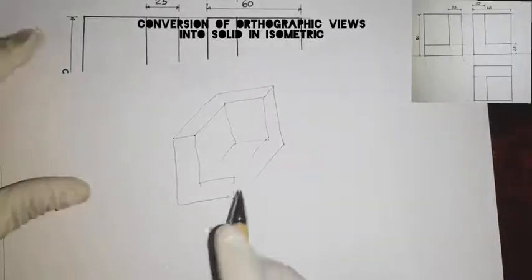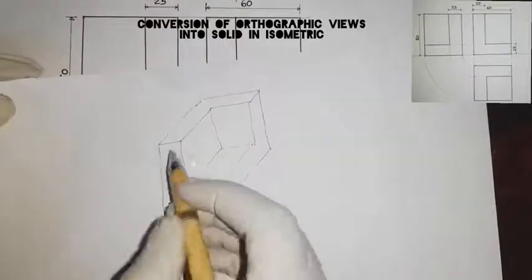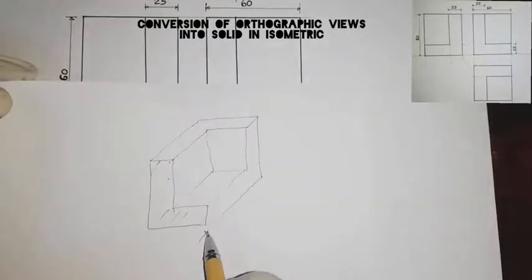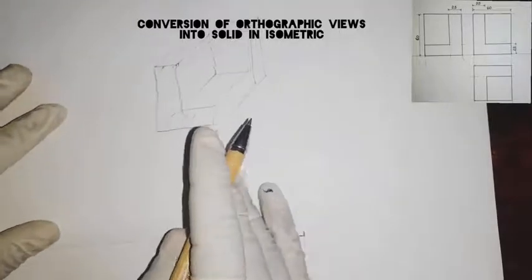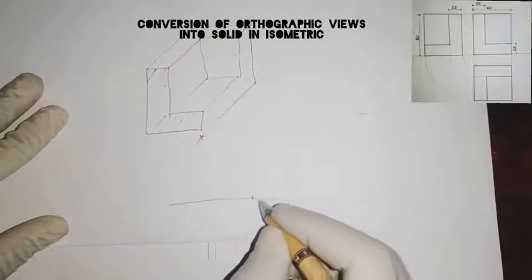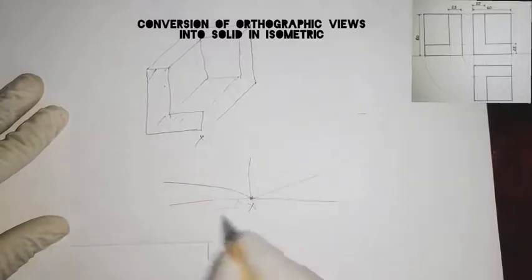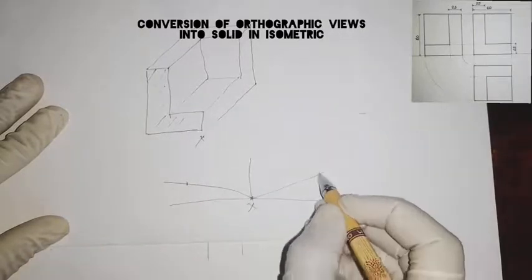And now because this is giving you the solid, this end here is the front, this one is the front elevation, and we are going to take this as the lowest point. Now, for us to draw this in isometric, we are going to first of all draw a straight line, then have point X there, then our 30 degree line, then our vertical, so that this side comes here, this other side comes there.